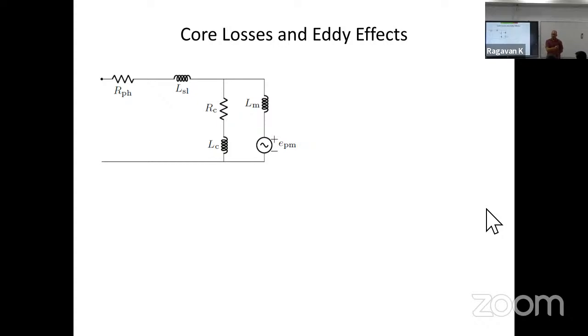If you take K_B out of that Thevenin voltage, you'll see that K_B reduces with frequency. When I say you are implementing an FEA solution without solving for eddy effects, what it means at the circuit level is that this branch is not present, right? This is applicable for the rotor core or stator core, anywhere.